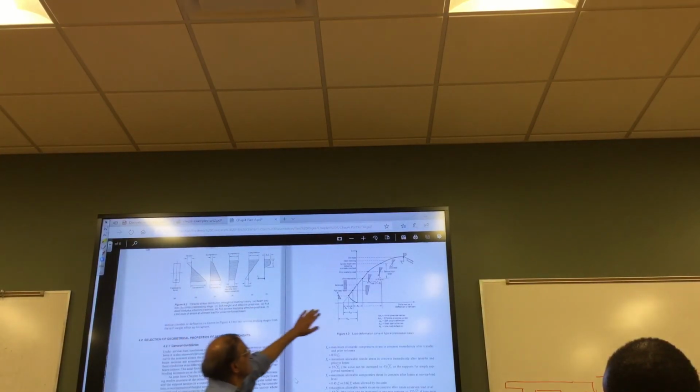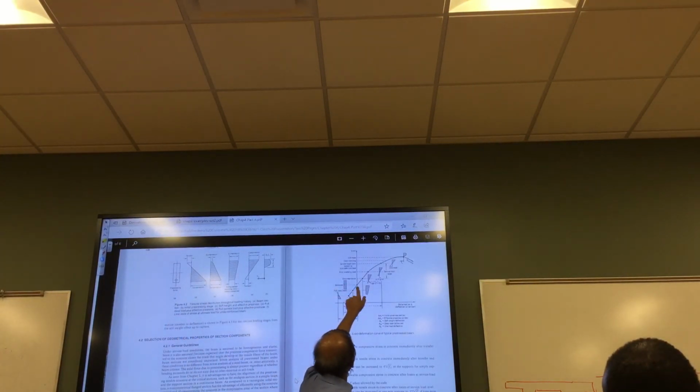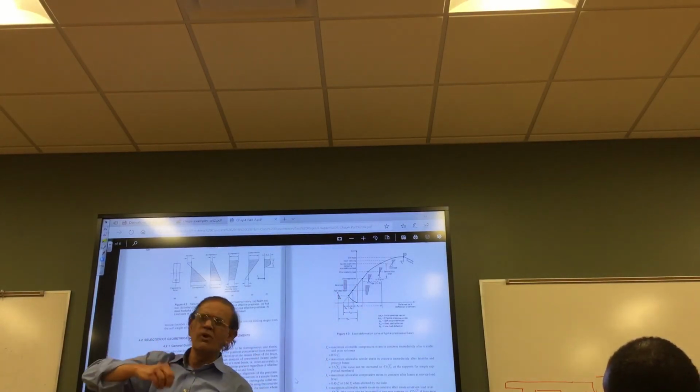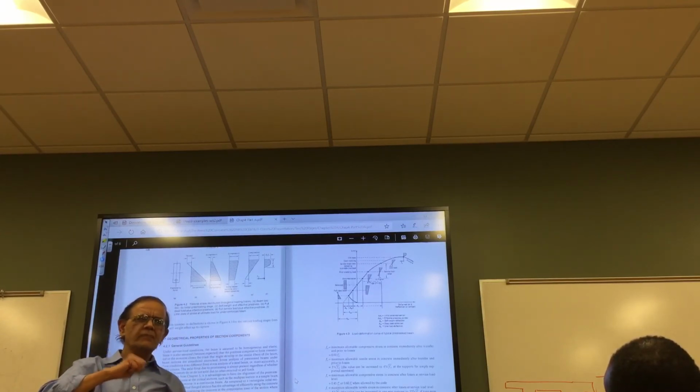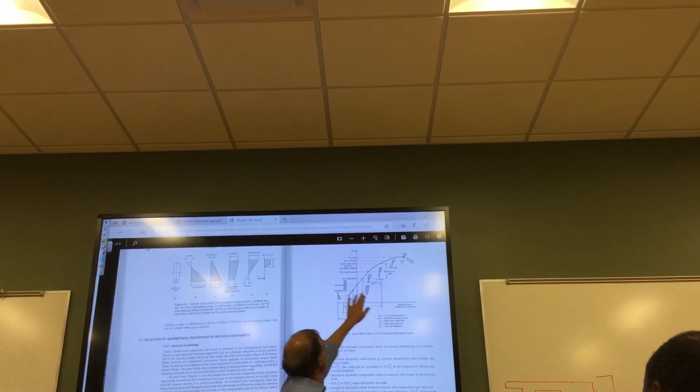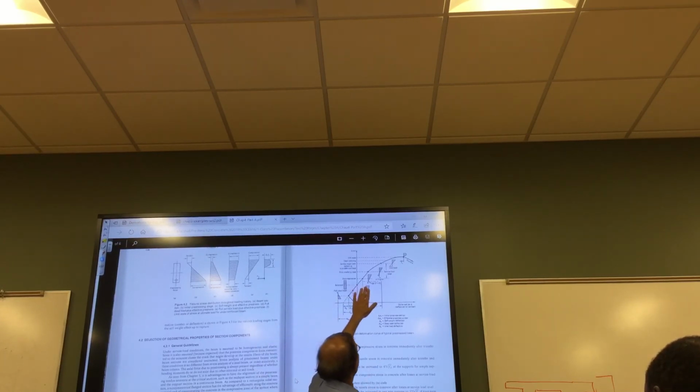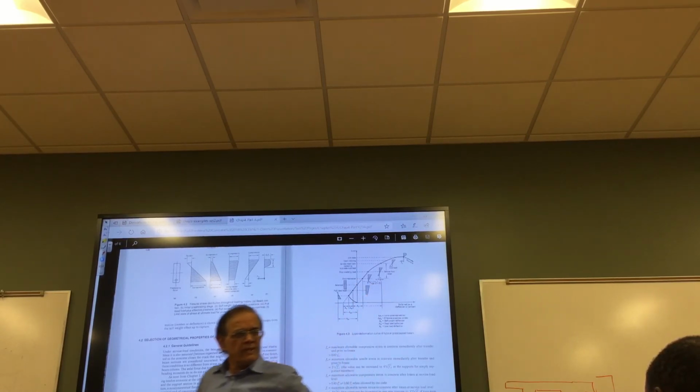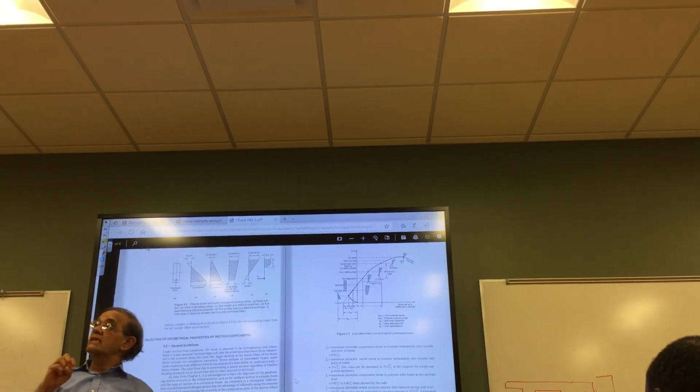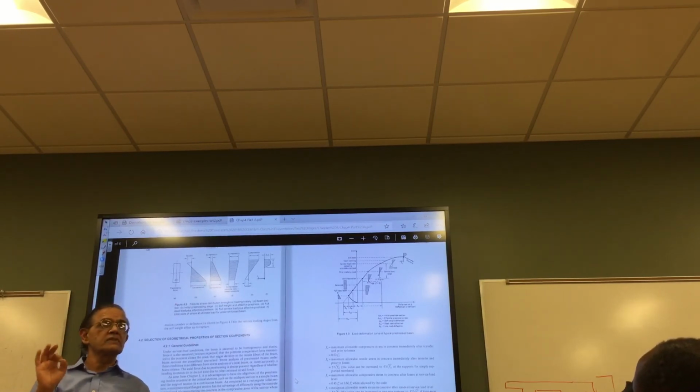You're applying the pre-stress. And then somewhere, as you increase more and more load, you come to a point where you're all compression and uniform. If you are adding the load in small fractions, that usually doesn't happen, but theoretically it is possible if you keep on adding sacks of something one by one. So you could reach this point, and this is interesting. It's called decompression. Right here, at the CGS, the center of the pre-stressing steel, the stress is 0, no compression or tension in the concrete.